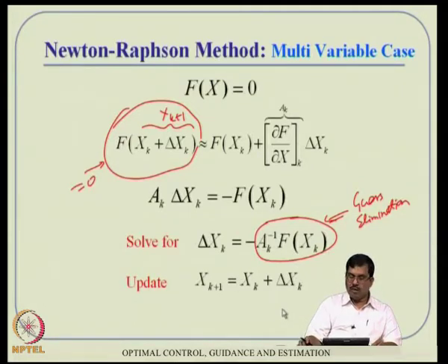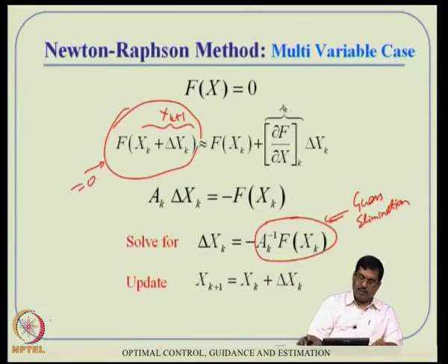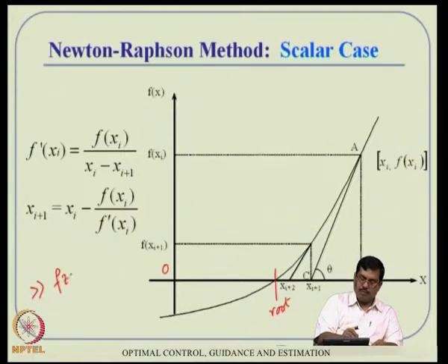And remember, in MATLAB, for those of you who are using it, for the scalar case you do not have to do all this yourself. If you want, you can do it, otherwise in MATLAB there is a function called fzero. If you use this function, it will try to find a solution around the guess value that you have to give.